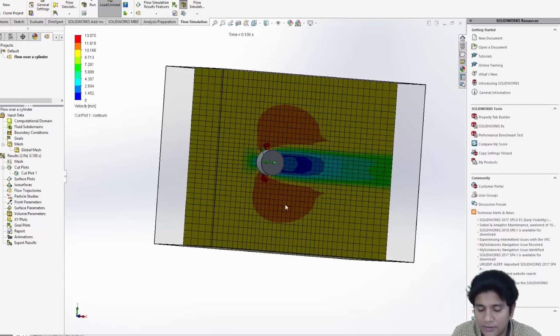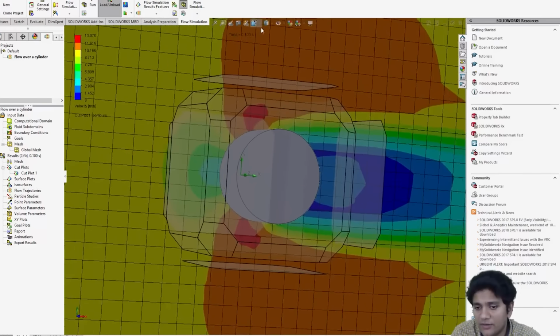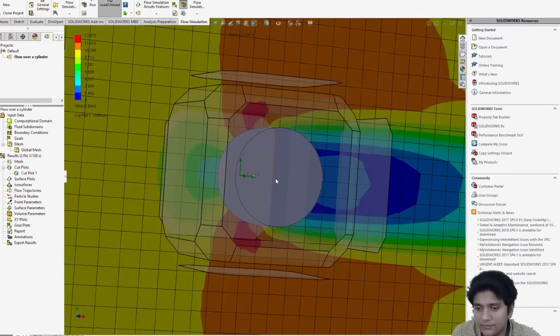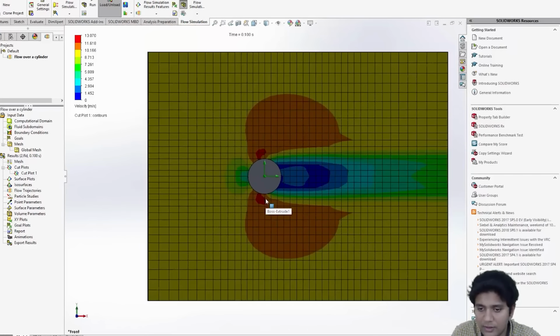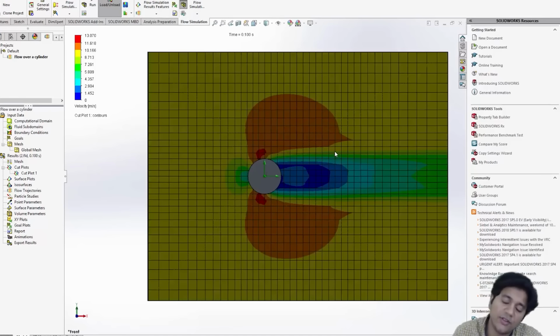So as far as the velocity distribution is concerned, we need to make a decision if it is right or not. So one thing as engineers you need to think about is whenever you're getting some results from a CFD simulation, you need to apply your judgment, see if it actually makes sense or not. All right, a couple of things that I wanted to do before that is just zoom out a little bit, and then I want to see how the simulation actually takes place. Since this is a time dependent simulation, we are calculating the flow solution accurately at each instant of time.